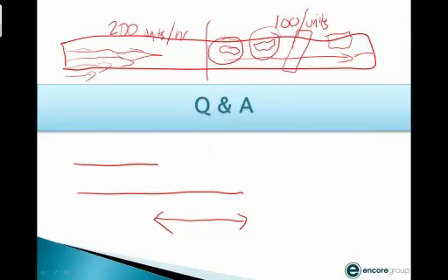So when you have the total time claim, when in this period is the delay, and you really can't just plug an activity in to show a delay. It's difficult. These issues up here at the top, all these different issues that came in, they're not specific enough where you can just plug them into a critical path schedule and see the impact to the completion. So measured mile is one of the best productivity analysis that you have.